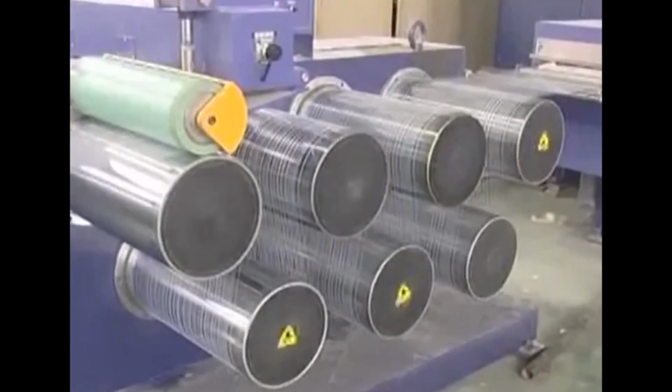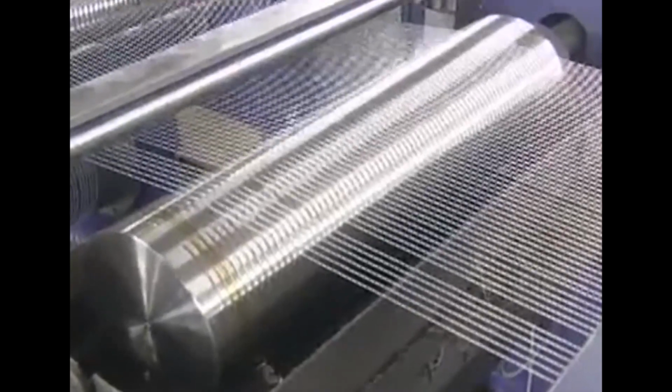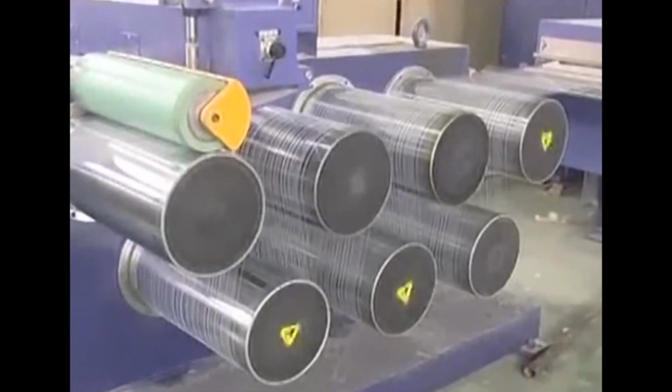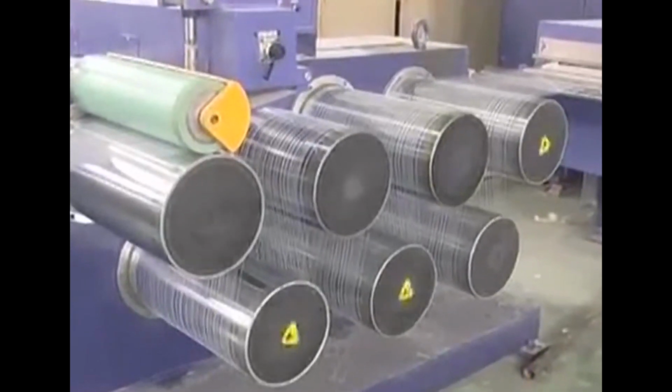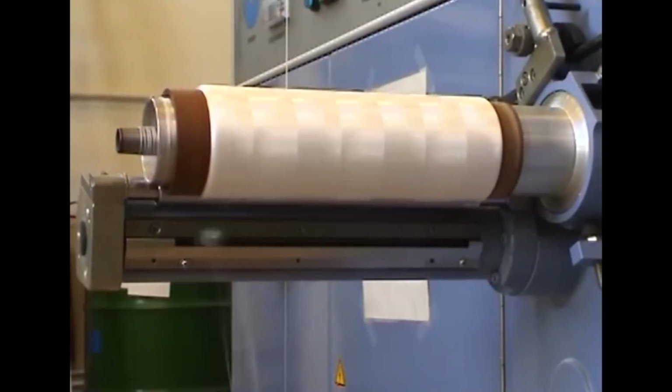So, when the filament is fed through it, the second one will pull it 4 times more than its length, and thus it attenuates the filament and also aligns the molecular chains to the fiber axis. The filament that comes out is wound on bobbins or whichever package they want, and then taken off from the chemical spinning.